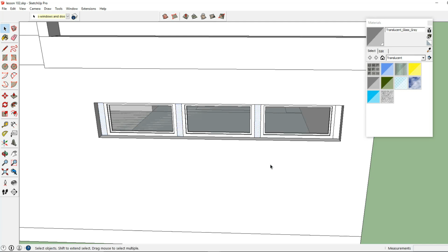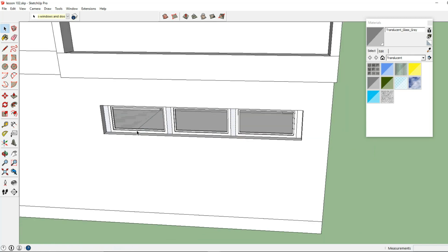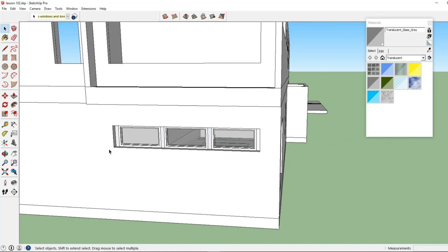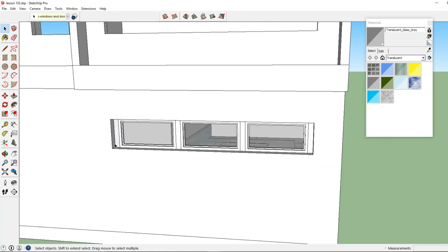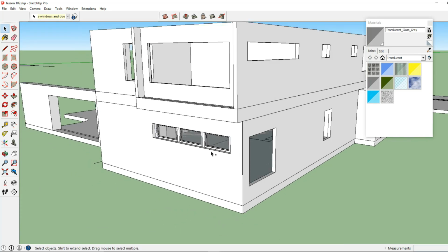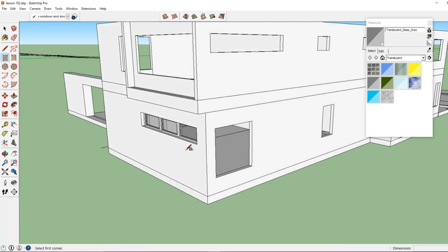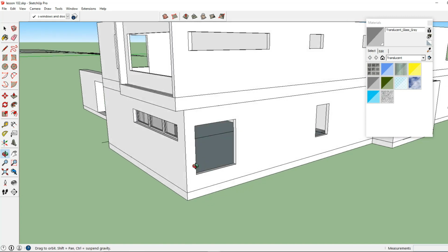One reason we reverse the faces is so that when I'm using the rendering software, Twilight Render, it actually treats the faces differently, and it's always good to have it on this white face. So just something I try to keep in mind when I'm modeling.